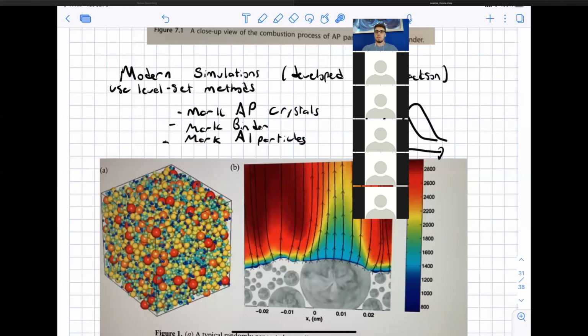And so the size distribution plays a big role. Even though for most heterogeneous propellants we know the ingredients are usually HTPB and AP with some aluminum and maybe a few other little things, like catalysts, which is rust, or iron oxide particles, to catalyze and control the burning rate, it's the size distribution and the exact mixture fractions of them used that are kept under lock and key.